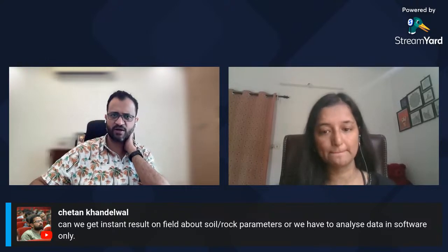Next question is again from Chetan Khandelwal. He is asking, can we get instant results in the field about soil and rock parameters, or do we have to analyze data in software only? That's a very good question, Chetan. At site, when you're in the acquisition mode, you are able to see the depth, inclination, the cone tip resistance, the friction ratio values, and your dynamic pore pressures.